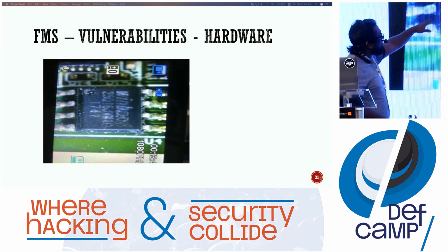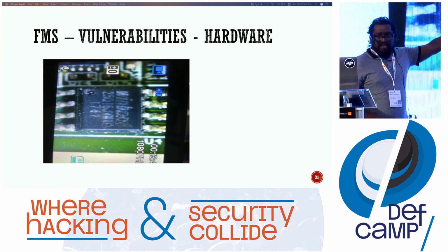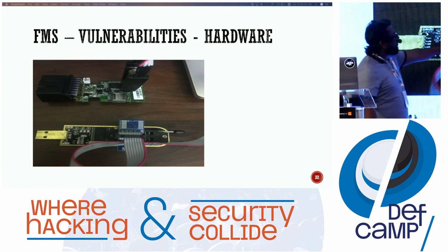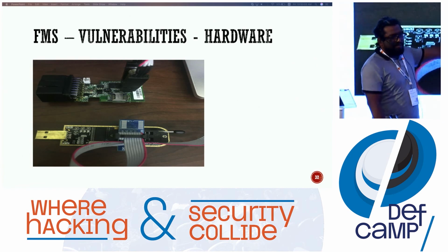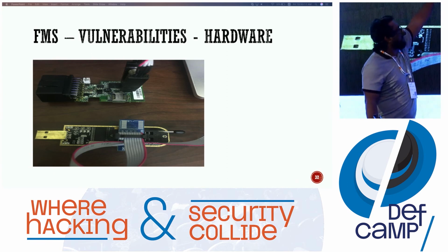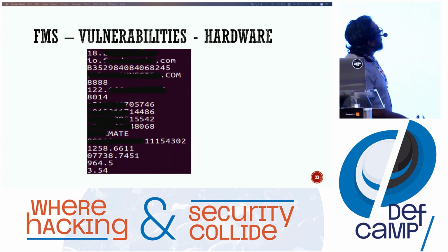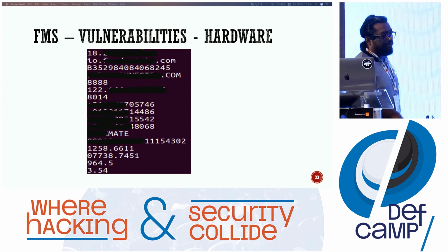So what we found was an SPI chipset, and we have the programmer, the CH341A programmer. We connected it to the SPI chipset and extracted the data, and we found this information from these things.